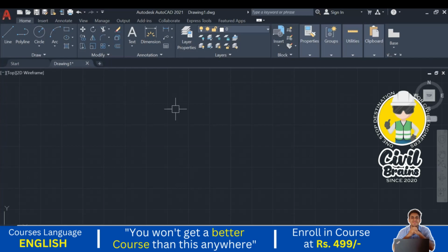So what are the dimensions of A3 paper? Let's see. I type limits in the command prompt and press enter. It is asking to specify the lower left corner. Our lower left corner is 0,0. Press enter. Next it is asking to specify the upper right corner.